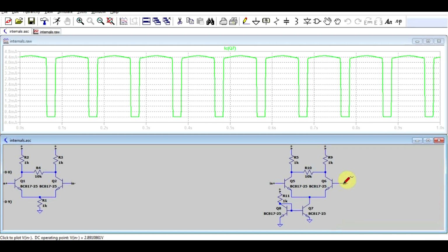Now if our input voltage goes to very high voltages, let's say 5 volts, as we said, the emitter needs to be roughly 0.6 volts below that, so 4.4. Now the collector emitter voltage on a transistor can have high voltages, so it can go up to 10, 20 depending on the transistor, but the minimum is the saturation voltage, which is, as we said, around 0.1, 0.2. So if we have 4.4 in the emitter plus 0.2, that's 4.6. That means that on our high side resistor, we've got 5 volts minus the 4.6, 0.4 volts.